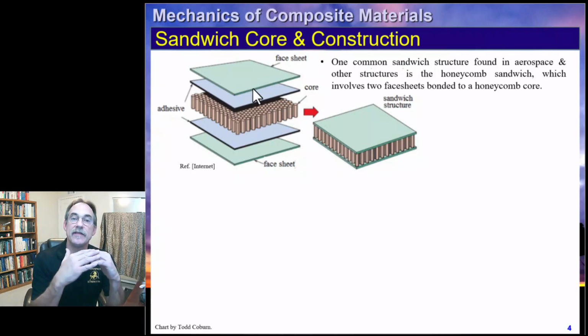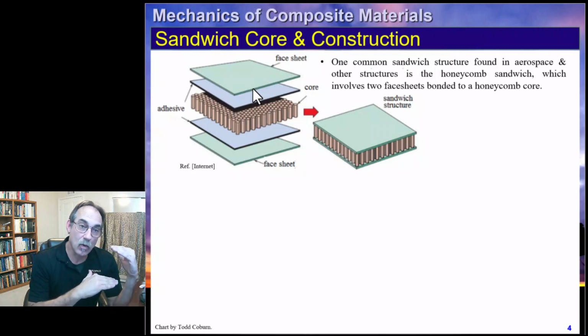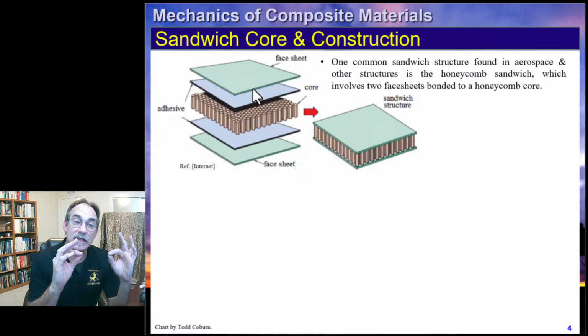So we're looking for something that has relatively good strength and stiffness for the face sheets. And because we're going to get our strength and stiffness by pushing them far away, these tend to be very thin. The thinner the better, actually. The reason we go with a thicker face sheet is usually because we need to withstand punch loads. If we just want to withstand more bending, we usually don't thicken up the face sheets unless we have a space constraint.